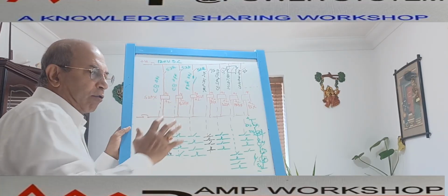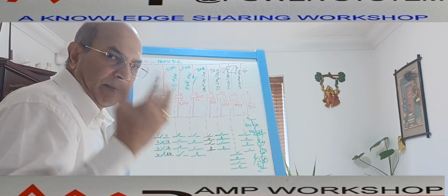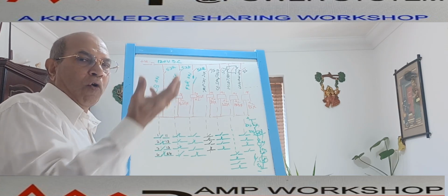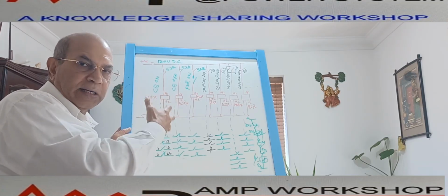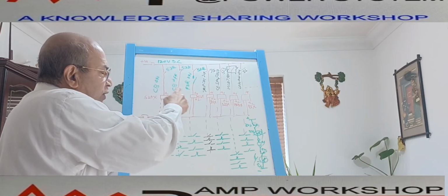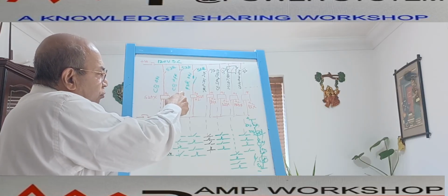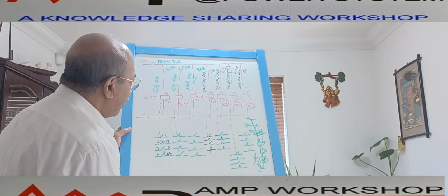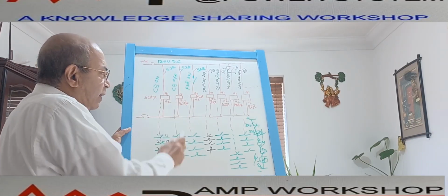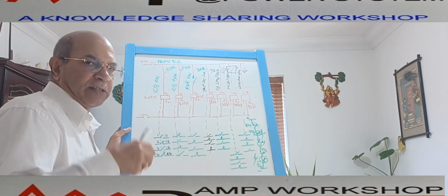Now, if for this breaker open position contact we need more numbers, in that case we have to use an auxiliary relay. How do we use that? One of the breaker's original 52B contacts we connect to an auxiliary relay coil. This coil has two ends, A1 and A2. Here we have tagged this relay as 52BX. 52B is the original contact, and 52BX means the auxiliary relay.